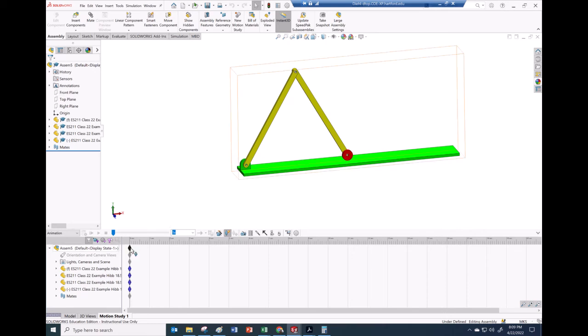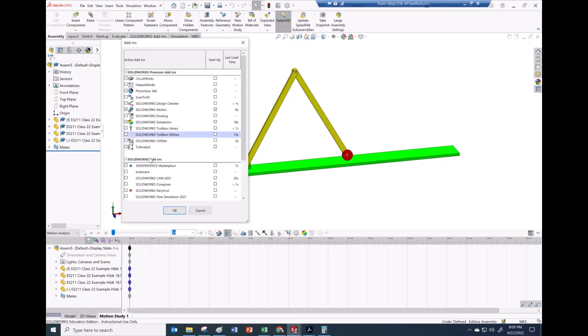around. And let's see, I want to change this pull down from animation to motion analysis. If you don't see that available, you need to do it as an add-on. If it's not available as an add-on, you have to use another computer that has a different SolidWorks on it that has motion analysis available, because it's an important thing to be able to capture the physics. Notice that it's right here. SolidWorks Motion in the add-ins needs to be available.